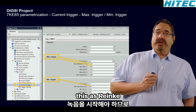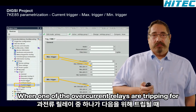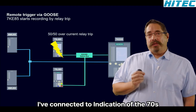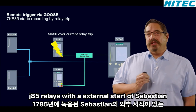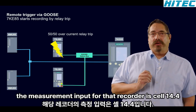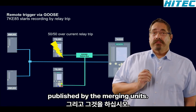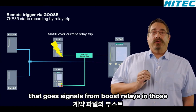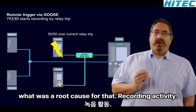However, we said that the 7KE85 should also start recording when one of the overcurrent relays is tripping. For that, I've connected the trip indication of the 7SJ85 relays with the external start of the fast scan recorder in the 7KE85. Keep in mind, the measurement input for that recorder is the 14.4 kHz stream published by the merging units. And do not forget to route the GOOSE signals from both relays into the COMTRADE file to get to know afterwards what was the root cause for the recording activity.